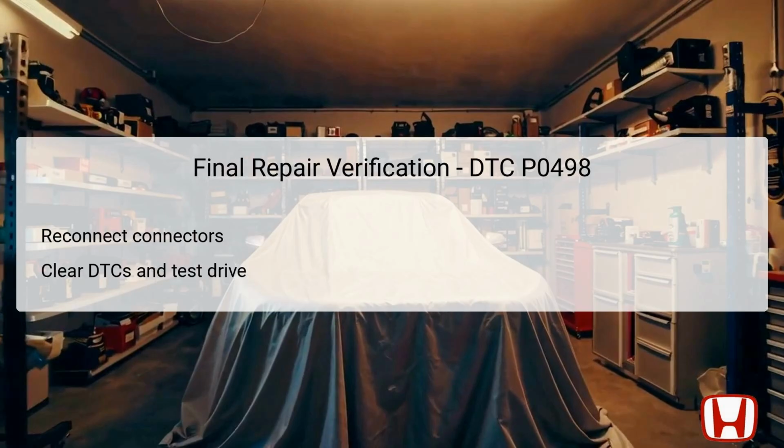The final step in troubleshooting DTC P0498 is the verification process, which is crucial for confirming that repairs were successful. After all electrical connections and components have been inspected and repaired, the technician should reconnect all connectors to ensure everything is properly plugged in. Following this, clear any existing DTCs using the HDS to reset the system one last time.